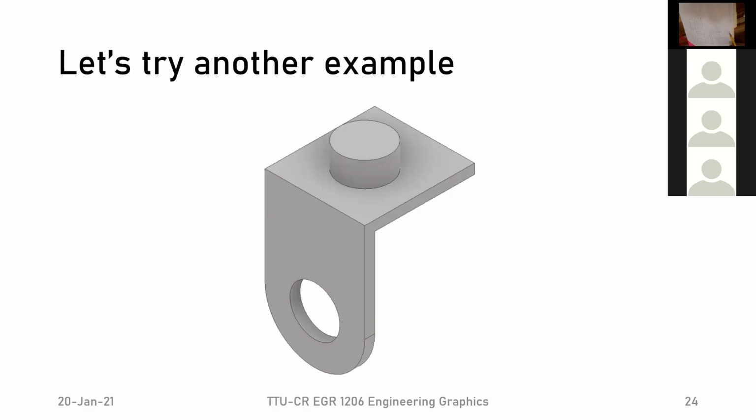Okay, so before we start adding all the center lines, we of course can't forget our little knob here, right? So we said the knob starts 2 in, so it'd be here, and we said it's too high, so our little cylinder would be sitting right up there. Okay, so now we have all the visible lines done for our right side view. That means now we have to look at any hidden views.